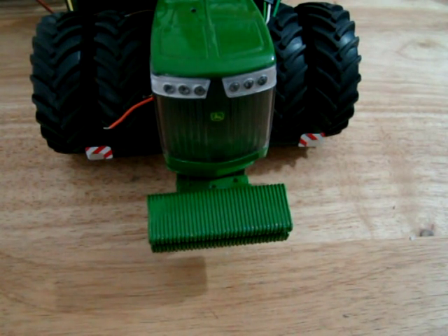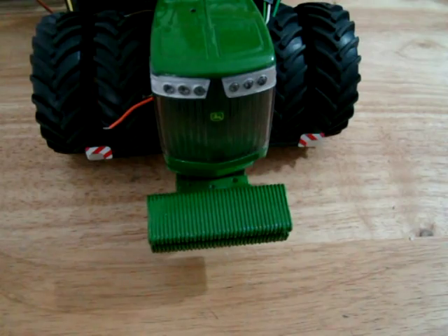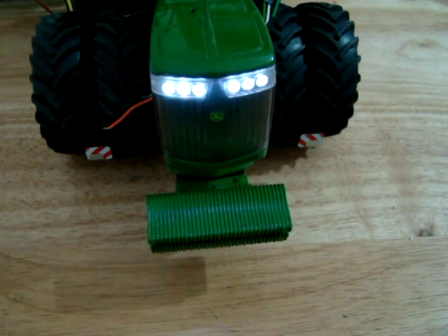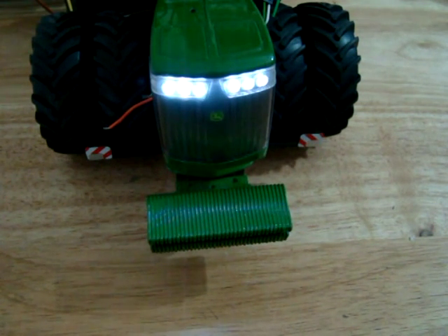Okay, now we've spun around to the front of the tractor. We'll test out our headlight. So we have our dips, should be 05. So there's our dips on. And if our pulse width modulation works well, we should now have brighter full beams. There you go, slight difference. So that's the full beams.